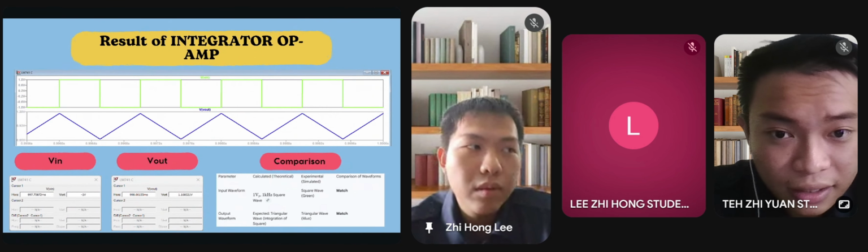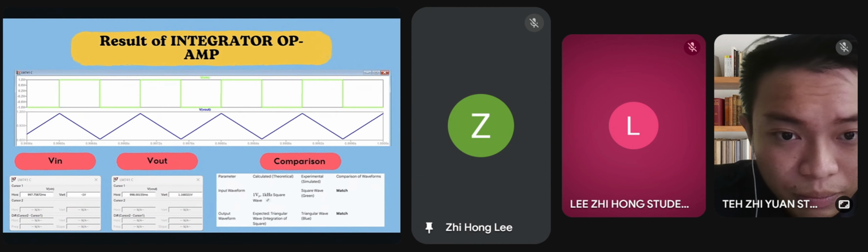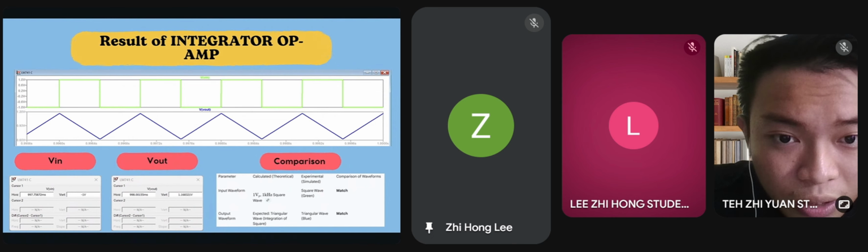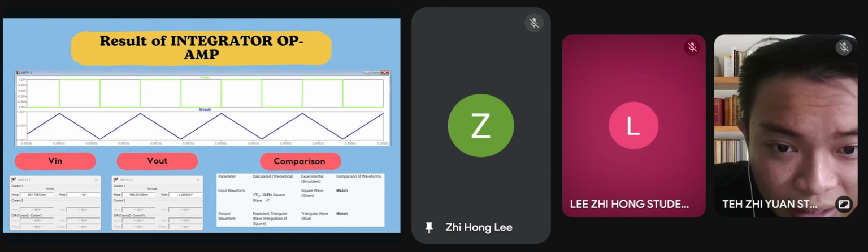I am Tazian, and I will now cover the dynamic circuits, starting with the integrator. The circuit successfully performed its function, converting the square wave input into the expected triangular wave output, while the integration function was ideal. We must discuss the 10 megaohm resistor present in the feedback loop.